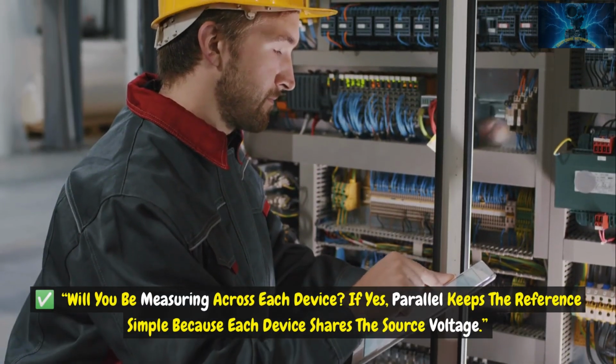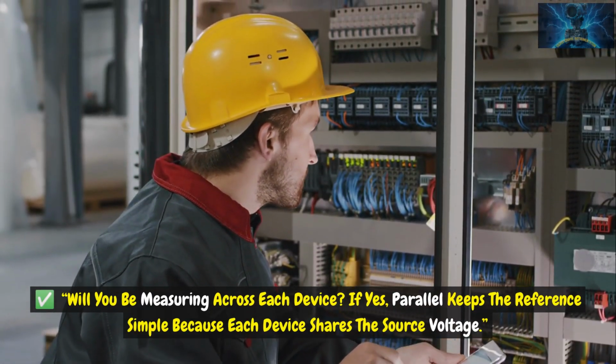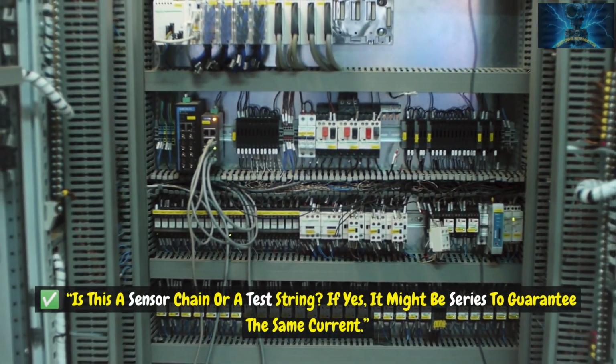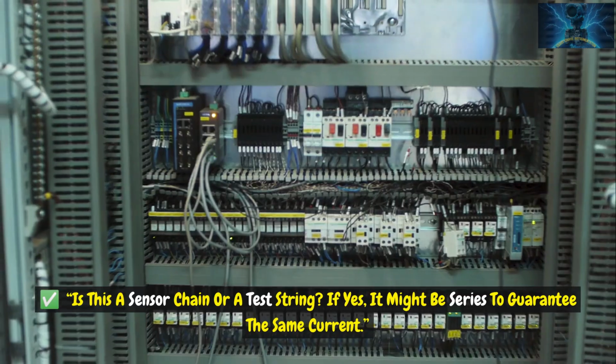Will you be measuring across each device? If yes, parallel keeps the reference simple because each device shares the source voltage. Is this a sensor chain or a test string? If yes, it might be series to guarantee the same current.